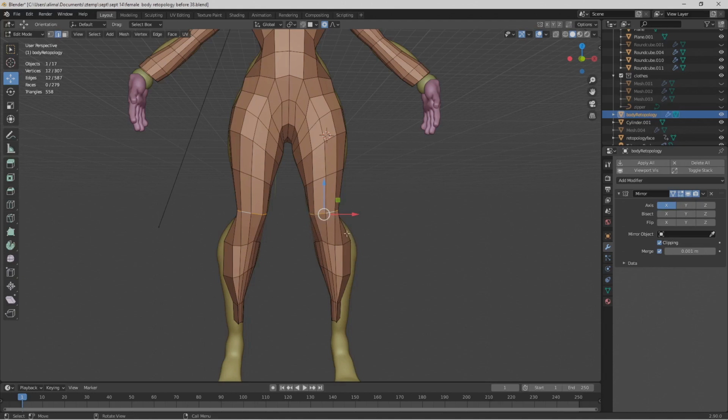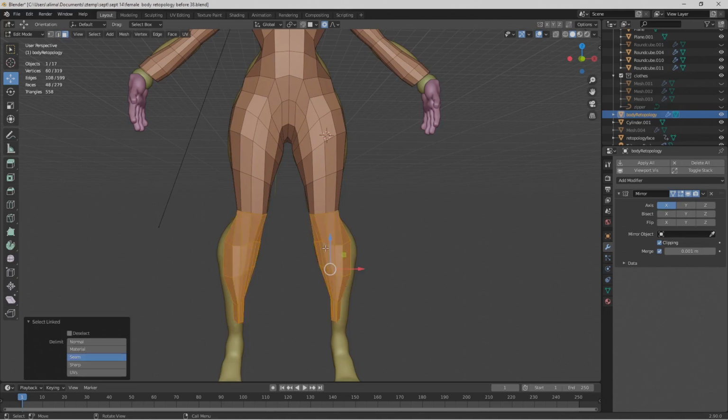So with this edge selected, I'm going to make sure that my mouse is underneath this edge. I'm going to press the V tool, which is rip. So I've ripped this geometry, which means I separated the geometry that was underneath this edge by pressing the V key. With that done, I'm going to go to the face select, hover over the geometry here, press L, then I'm going to press X to bring up my delete button, then select faces to delete.